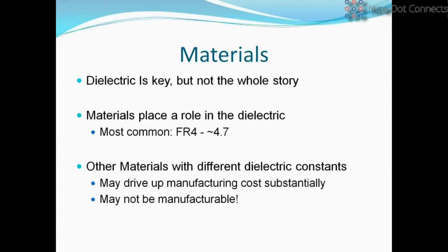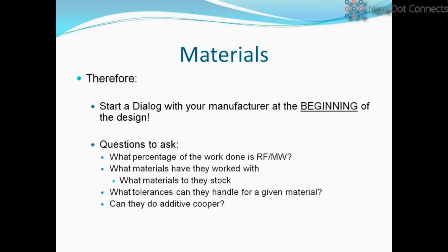And so what I want to drive home here is that before you start putting anything onto your PCB, you can work the schematic to your heart's content, get it through review, get your bill of materials done, make sure your libraries are clean. But before you start doing any placement or layout on the PCB, your layer stackup and your materials must be known, and that means you've got to have that conversation with your manufacturer.